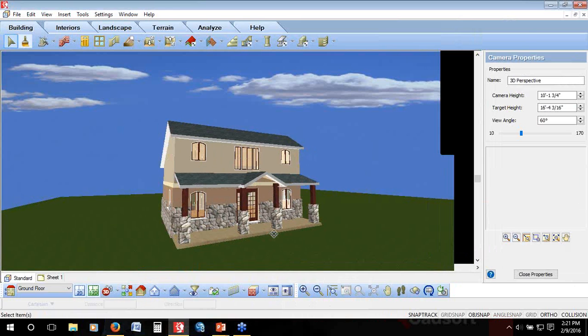So again, when you're creating a roof, first step, always, is it roof by perimeter or roof by picking points that I need? Once the roof is on, they're both going to function the same way. And the next step that you'll always do is, where are my gables? Do I have a gable end? Is there an end that's on a shed roof portion where I would not hang a gutter and I wouldn't hang an eaves trough? Maybe it's up against the face of the house, like our back edge is here on our veranda roof. You're going to make those gables as well.